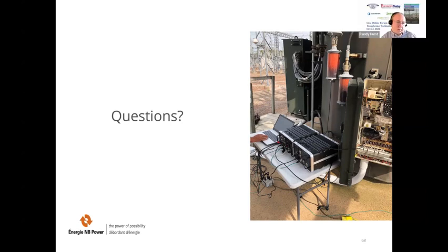But it was only the motor current and the DGA, the dissolved gas analysis. So in fact, that is why we are pushing the Vibro-Acoustic, the DRM, and the motor current combined. All these three can give you a good picture of how your tap changer is working.